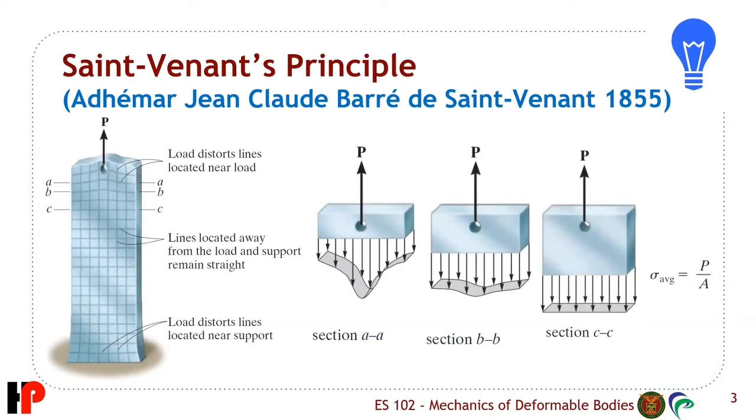So the repercussion of this principle for ES102, when we deal with stresses, is that what we're actually analyzing should be sufficiently far from the point of application. So that is the repercussion of Saint-Venant's principle for our analysis.